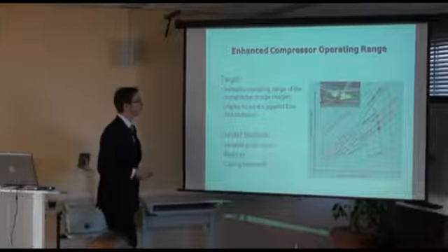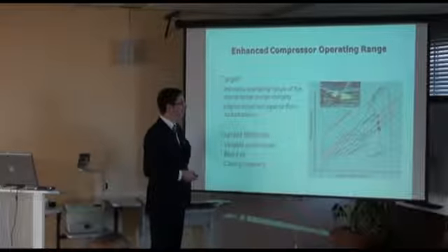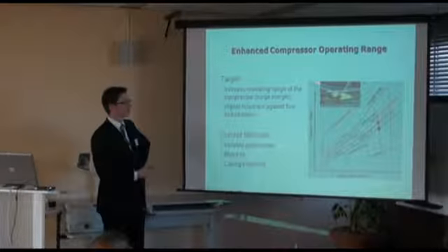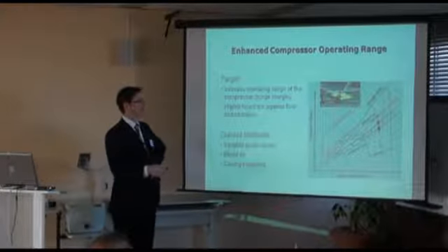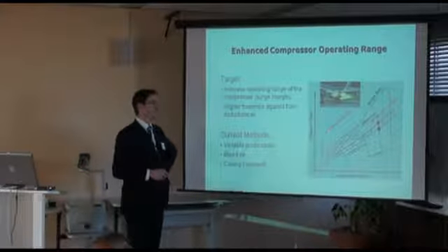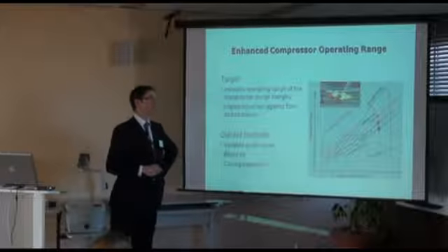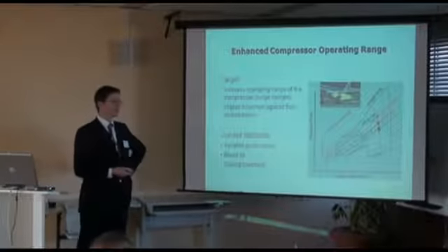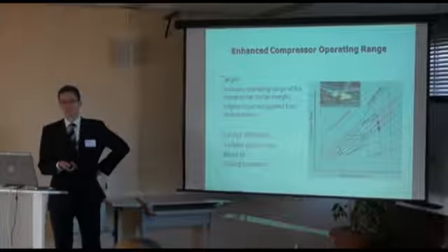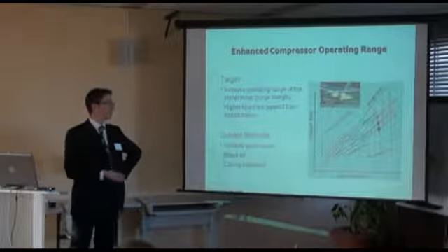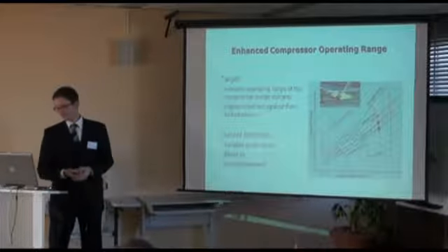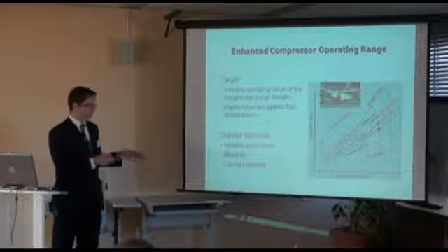Once you cross that limit, you will see that sometimes you can have complete backflow. The flames will come out of your fan, also taking the oscillatory part going through the turbine. And maybe you will even lose your engine here, or at least some of the blades are contained in the backflow. The important part, at least you will lose your thrust, and especially during takeoff, that's a really undesirable case. So we've got to avoid that.